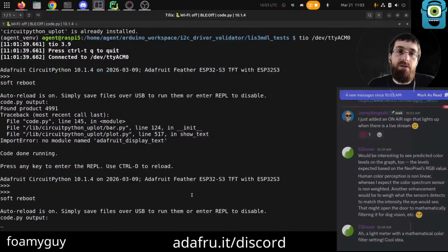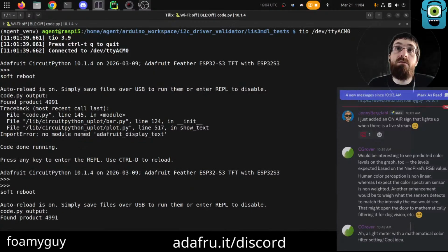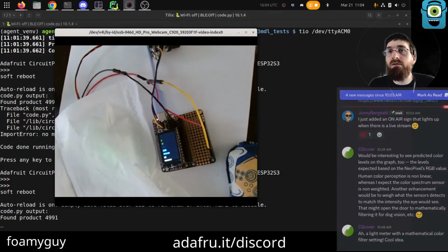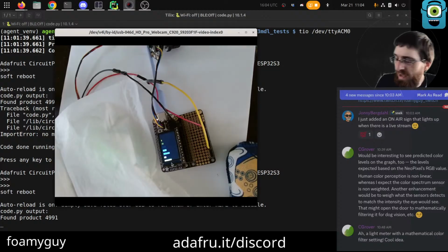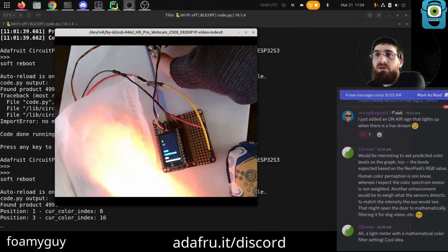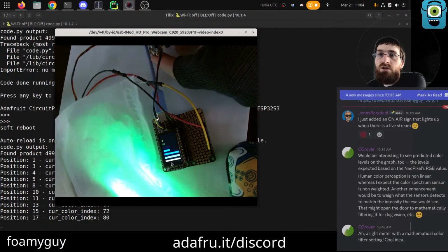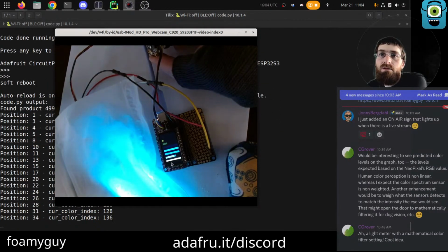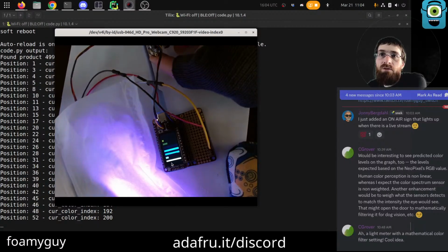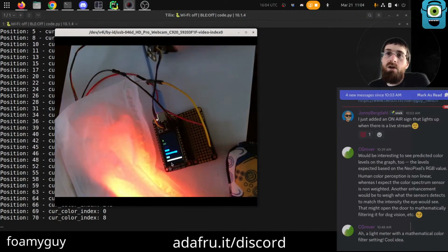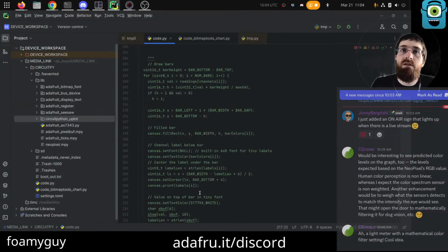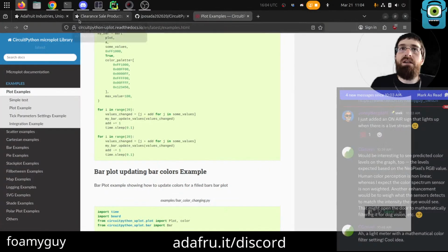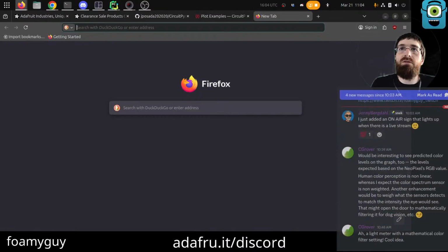Now it should be able to run. At least try it for the next thing. Nice. Okay. Yeah, that worked. Okay, so there's like a padding. I don't know if that was padding between bars or not, but there's actually kind of a lot of space between bars. And then the colors are totally messed up, right? The colors of the bars are like all blue and teal and wrong. So that is the 565 problem. One thing I don't remember, so I converted those. Did I convert those to 565?